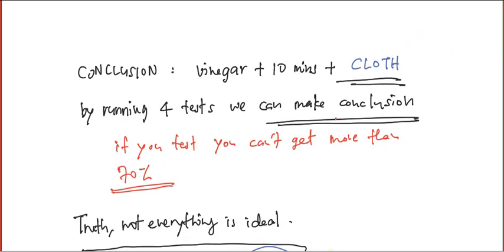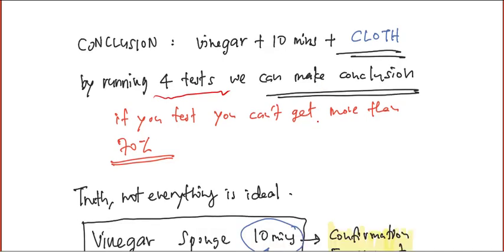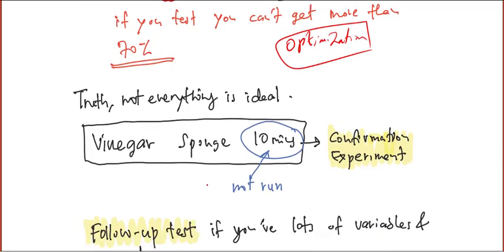As you can see here, this is our result. We reached this conclusion by doing only 4 tests, and we just have the results for 4 tests. Then we can make a good decision about which combination of the tools, material, and time can be used to get the best result, and this is called optimization by the Taguchi method. Okay, so this is one method for optimization.